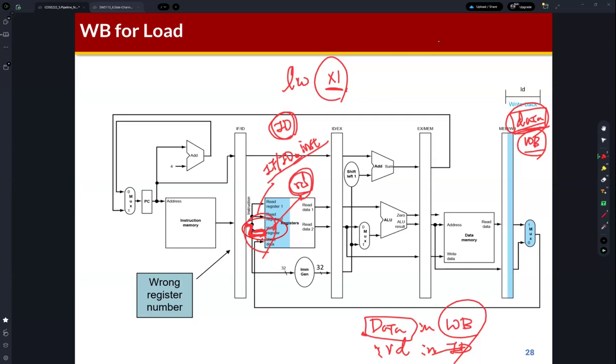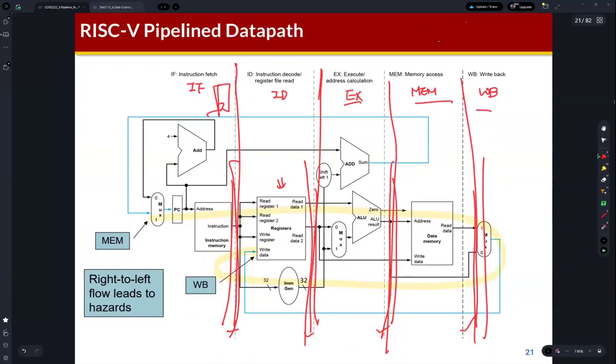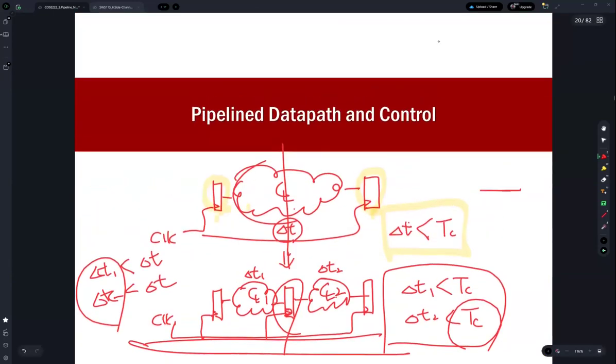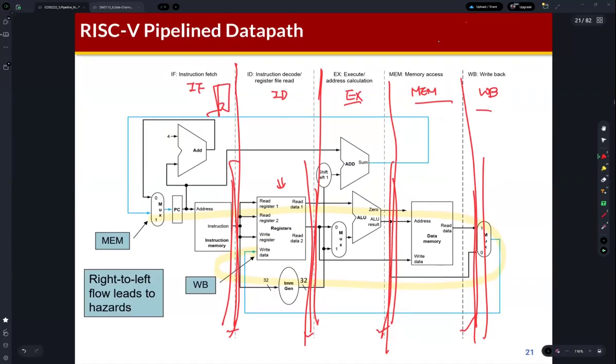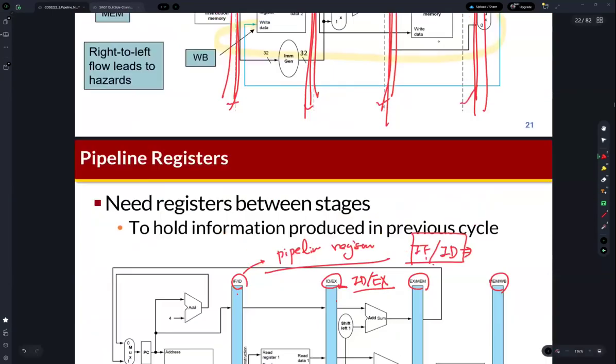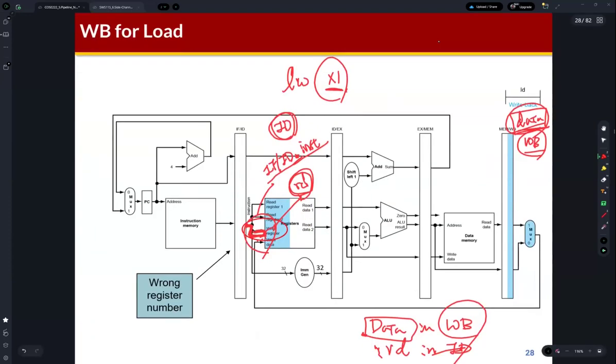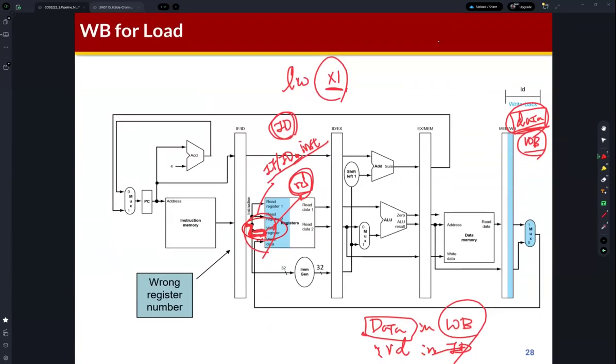So actually in the pipelining design, this is the tricky part. Actually, this is not difficult. Based on the common design process, we can just insert the D flip-flop in the combinational logic path, right? But in order to support correct operation in the pipeline design, we need to match the timing of signals.